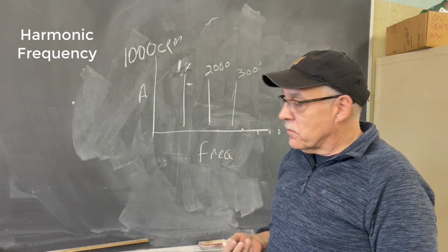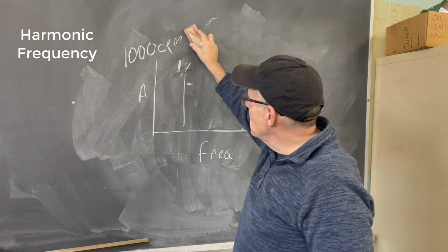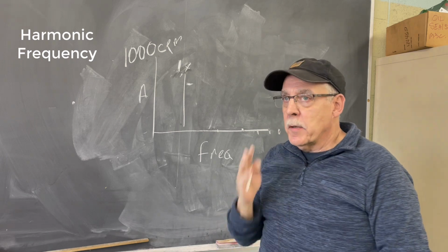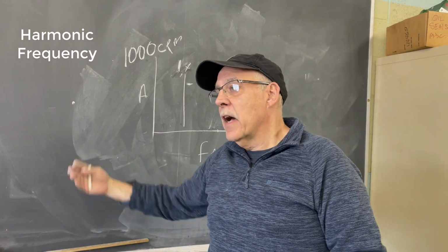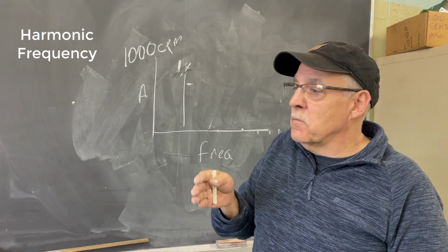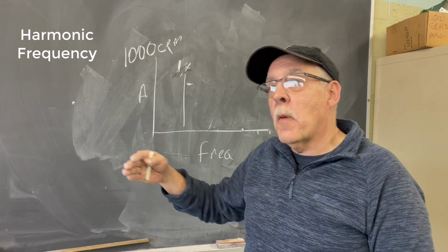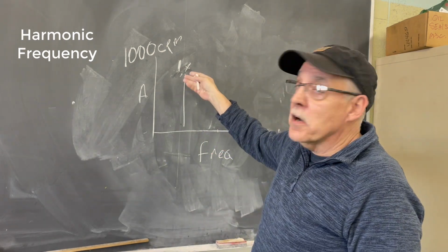The only one that really has no harmonics of the fundamental frequency is imbalance. Imbalance will show up at one time only. There won't be any harmonics of that. But a looseness, there would be 5. That's how we tell looseness. The more harmonics there are, so looseness or whatever is just a multiple of running speed.